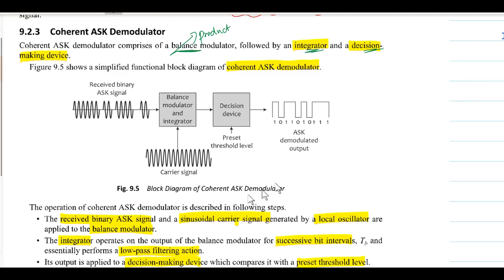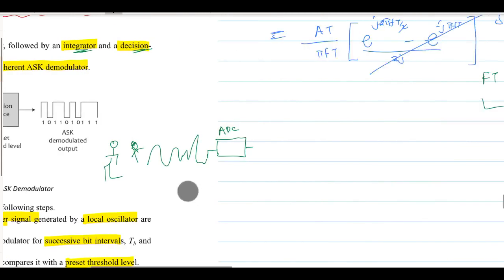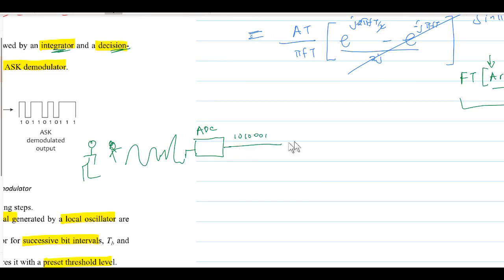So we will see in a few steps. Of course, this is the diagram. This is now at the received signal. When we're talking about the demodulation, just to be clear, we are at the source. We have the sound. Someone is talking at some point. The sound is received by a microphone, which produces an analog signal. This analog signal is sampled and quantized by the analog to digital converter. This generates for us binary streams of ones and zeros, and this signal is taken through a pulse encoder, PCM. This gives us a line code, which is the one we are referring to as the unipolar non-return to zero. Once we have the unipolar non-return to zero, this now becomes our binary stream.